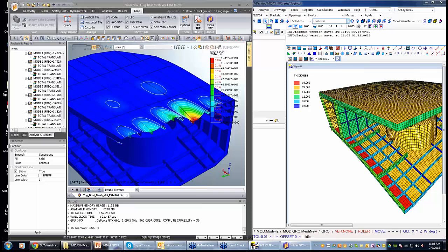The difference depends on the meshing size that you choose. If you have a fine mesh, the whole stiffened panel can be defined from shell elements, and it will be exported and imported into Midas NFX like that. If you have a coarse mesh, then you can have a deck plating defined by shell elements, and stiffeners defined as rods and beams.